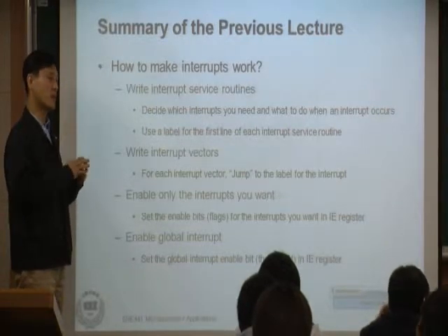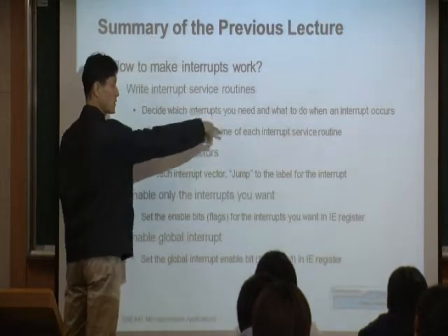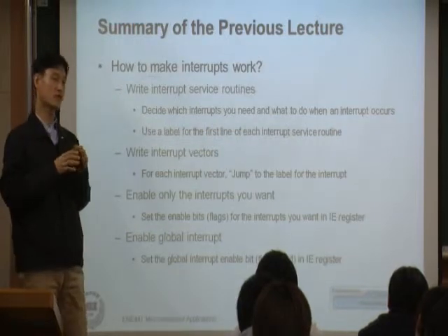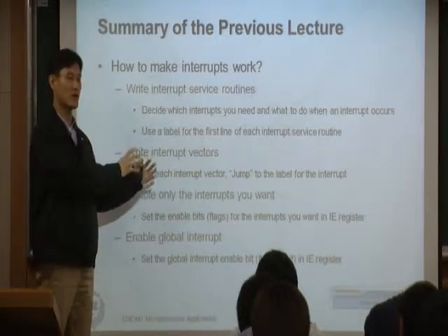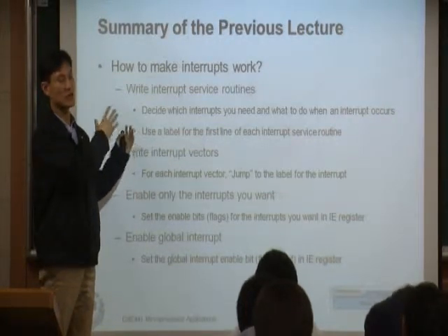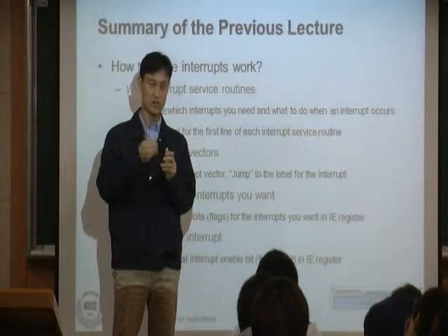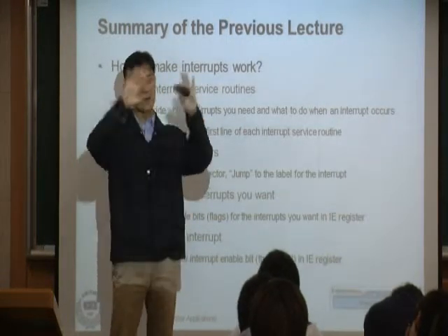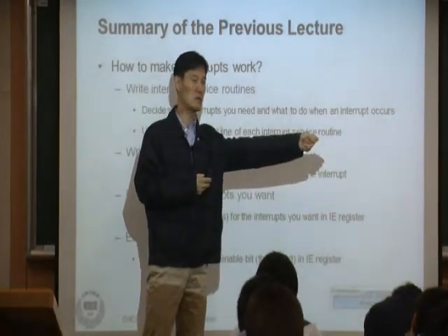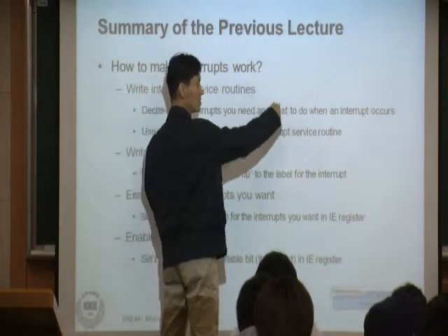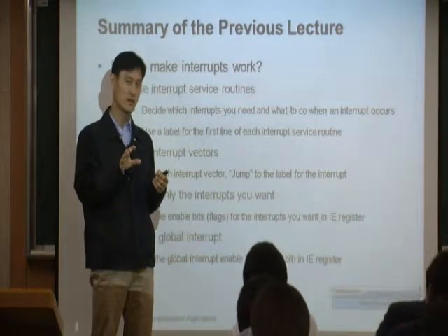But let's say you want to enable the timer interrupt. In that case, again, you set the global interrupt and timer interrupt bits to 1, but you also have to set the timer registers. Only then will the timer work. We need to have timer hardware. That's going to be the interrupt event. For example, coming back to your telephone example, let's say I have electricity in my home, which is the global interrupt, and I have a telephone plugged into the wall outlet. That's like enabling the timer interrupt. But your friend has to call you. That's the interrupt event. Only then does the telephone ring.